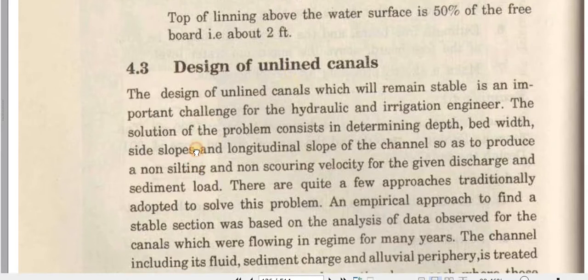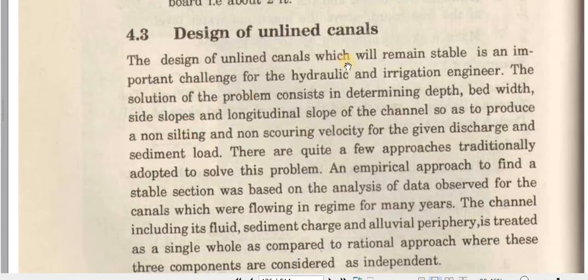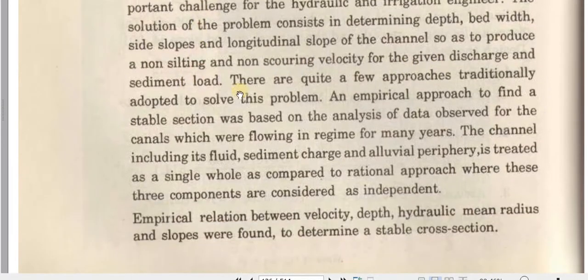Design of the unlined canals. The design of unlined canal is a greater challenge, and the design should remain stable. It is an important challenge to researchers and designers. The solution of the problem consists in determining the main factors like depth, bed width, side slope, longitudinal slope of the channel, so as to produce non-silting and non-scouring velocity for the given discharge and sediment load.